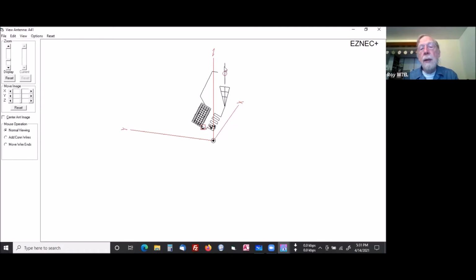Then I had another antenna over here, on a different frequency, which I had to make so as not to interfere very much with the other antenna. They had to be fairly independent. This line here is the transmission line going up to that dipole, and it's not connected right at the moment for an analysis. This was a design I did as a consulting job. It went into a winglet of a drone.